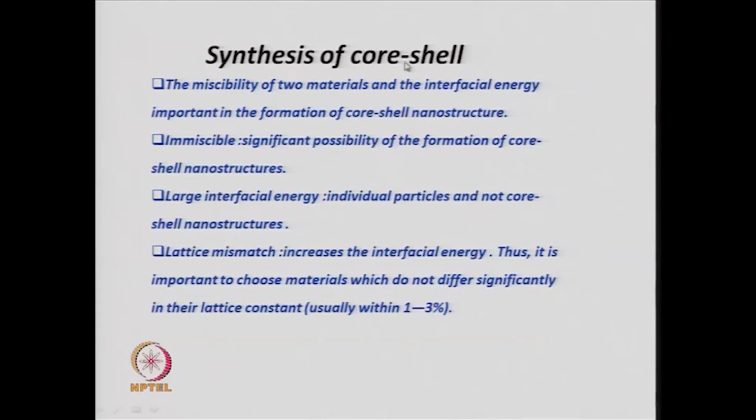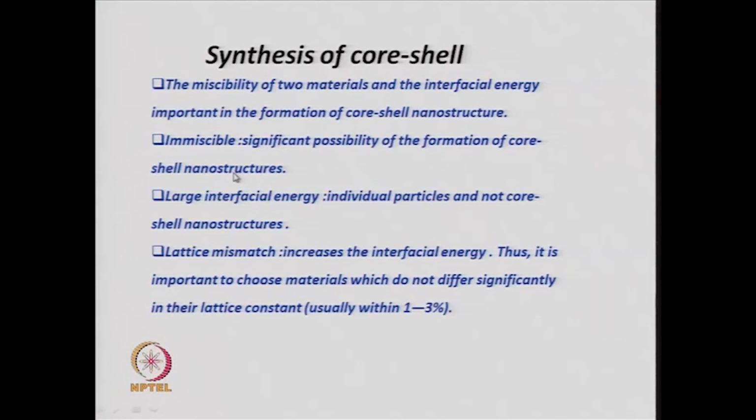Now, the synthesis of a core shell nanostructure can follow basic principles, which are the miscibility of two materials and their interfacial energy. That is very important when you design a core shell nanostructure. If they are immiscible, there is a significant possibility of forming core shell nanostructures. However, if they are miscible, then they may form a solid solution. So, this immiscibility is important.